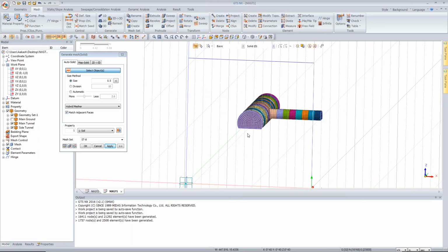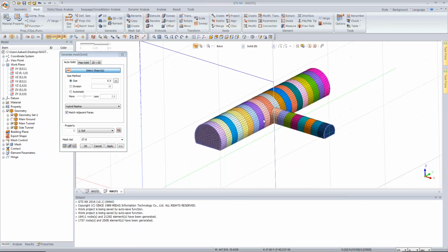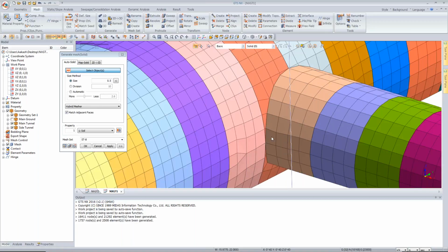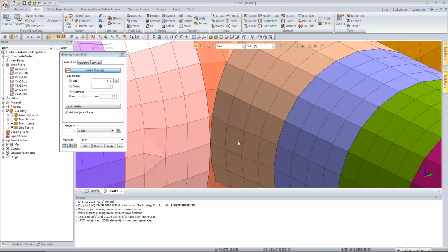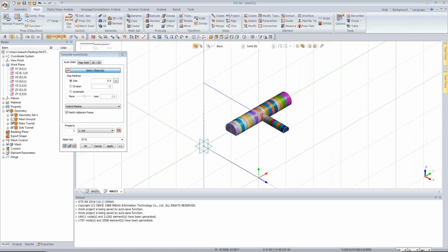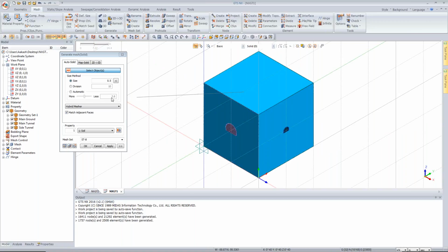Fine. The meshing is done, and the program takes care of the nodal connectivity, okay, no issue from that point. Okay, so once you do the auto connect, the program takes care of nodal connectivity, and finally you have the main ground. So I'm just saying select 3D mesh size, and I can give it a name as main ground. I'm sorry, not main tunnel.